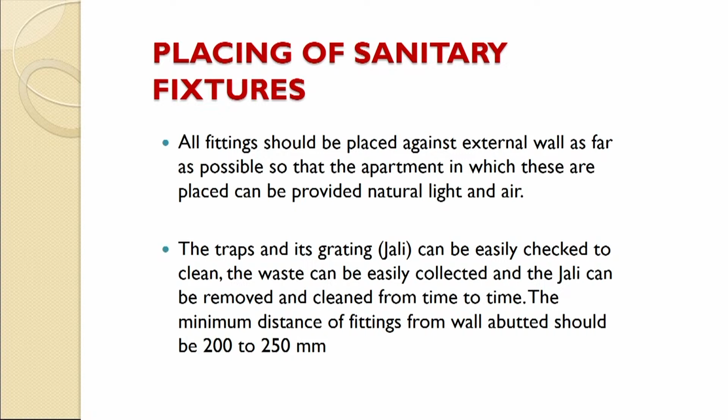Another thing is that the distance between the valve and the fitting should be between 200 to 250. It is not a very strict standard, but as common sense, you should keep an appropriate distance.